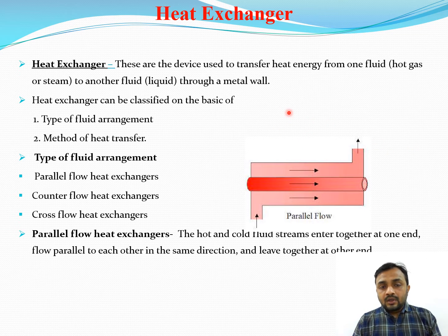Our next topic of discussion is your heat exchanger. What is a heat exchanger? Okay, a heat exchanger is a device used to transfer heat from one fluid to another fluid. The device by which we transfer the heat from one fluid to another is known as a heat exchanger. Heat exchangers can be classified on the basis of the types of fluid arrangement and the method of heat transfer. According to the types of fluid arrangement, the heat exchanger is divided into three types. One is your parallel flow, one is your counter flow, and one is your cross flow.